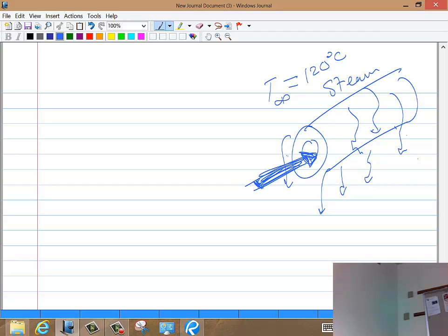So that's the Arkansas River, and the water coming from the condenser comes here, goes to those cooling towers. This is the place where they dump the water on basically a PVC tray, and there are fans over here that suck the air. The air comes from the side, those are the inlet filters basically. The air comes, hits the water, cools it, and then leaves.